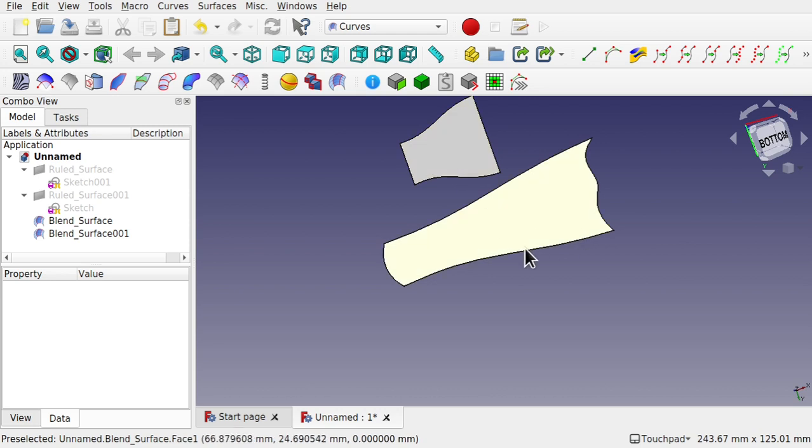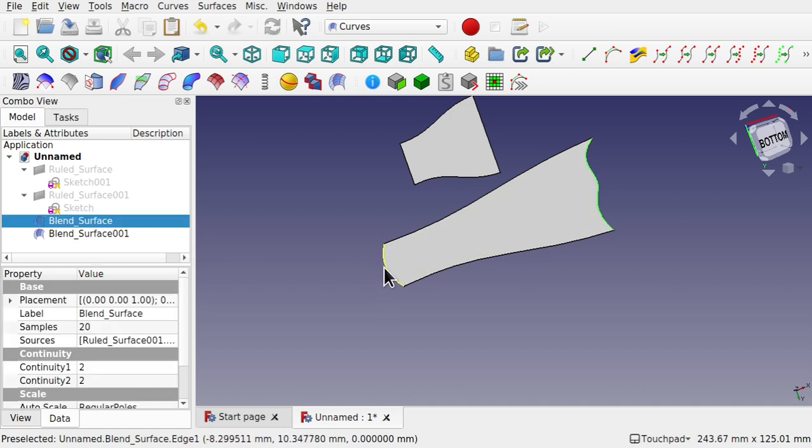So although this is shorter, you can see the differences in shape. A kink comes down here, and because we selected the back edge, the blend is much more in association with that back edge to this front edge here, and I've connected up the two B-splines here